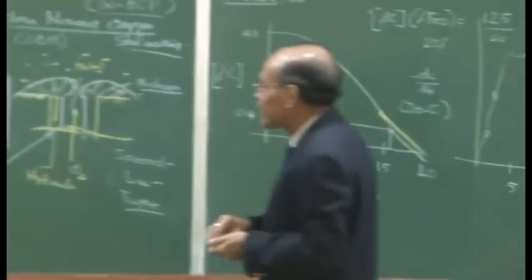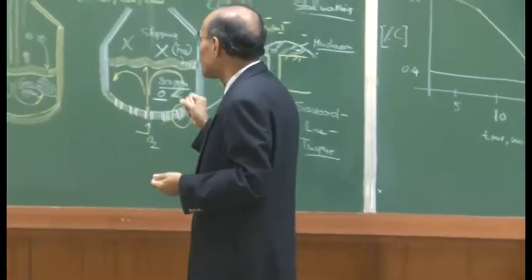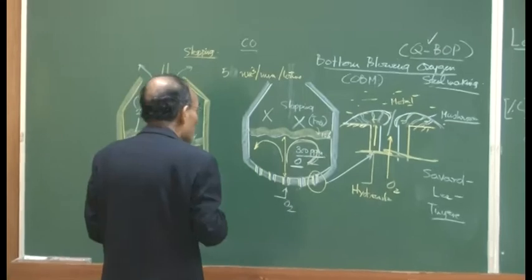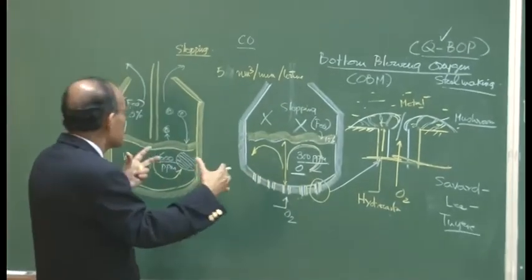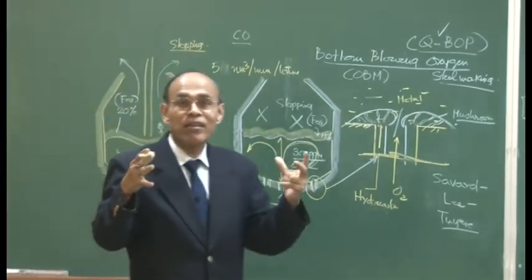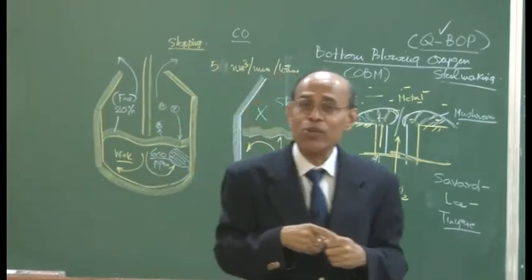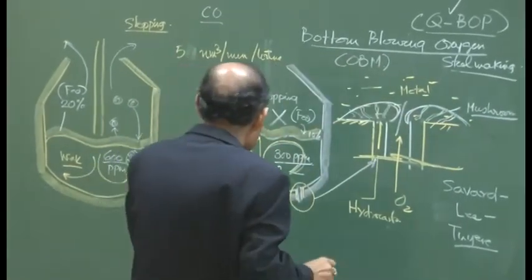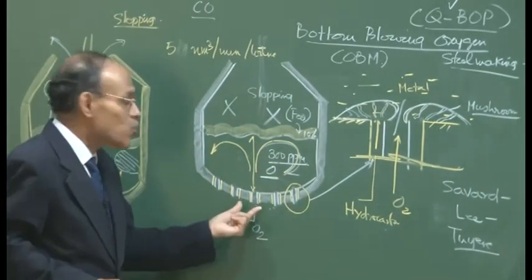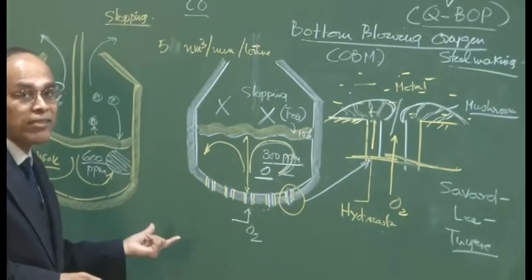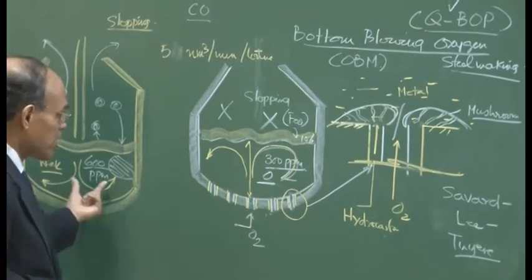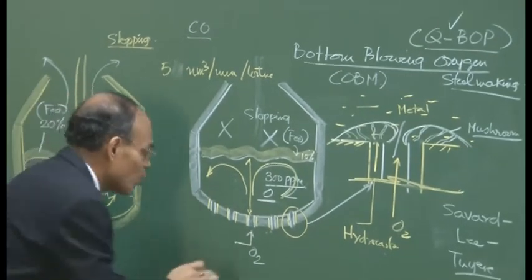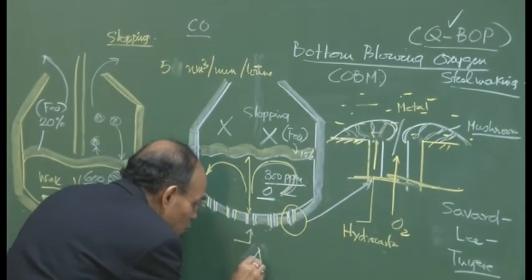So we will extract the characteristics of the bottom blowing as well as the top blowing process, and perhaps a win-win situation is what is known as the combination blowing steel making process, or the bath agitation process. Particularly the bath agitation process solves many of the problems of the two reactors I have discussed today, whereby we will not introduce oxygen, but argon.